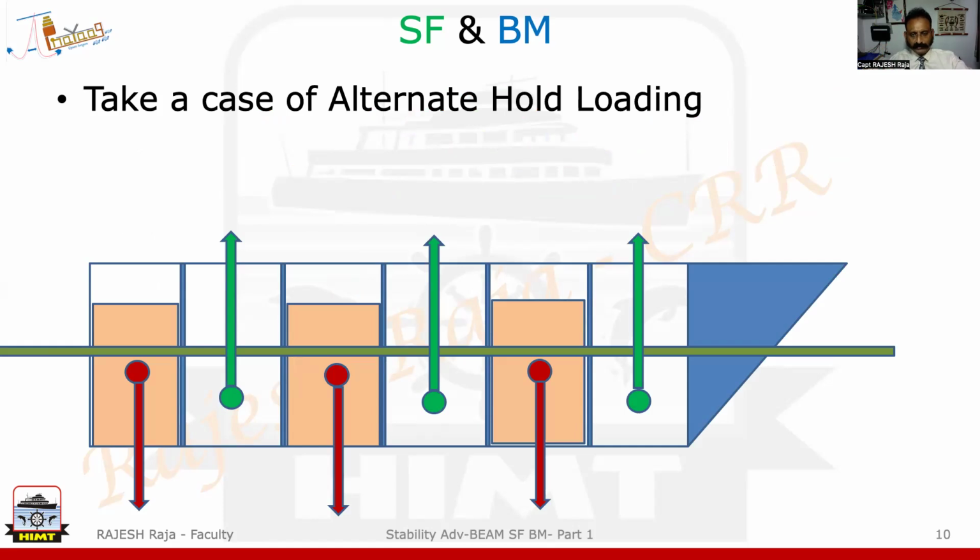Now, similarly, I've shown you the force of buoyancy acting quite strongly at the empty holds, even though the filled holds also, on the underwater volume which they have outside, have force of buoyancy. But you will see they will act more on this empty space. Why? Because there's nothing to cancel here.